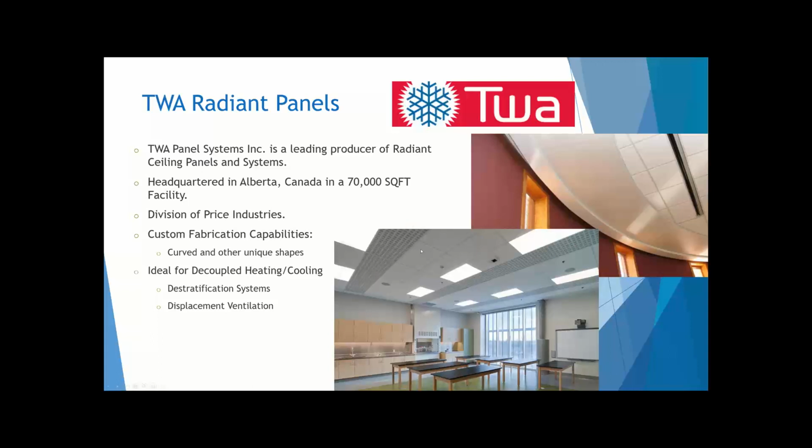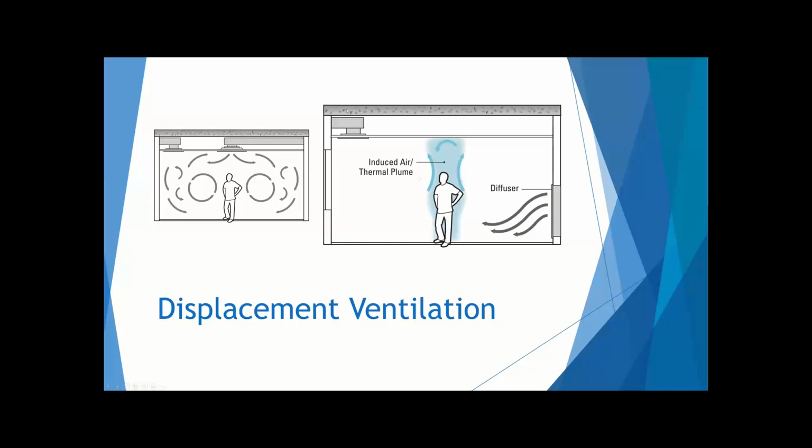So what that does is that heat actually hits the floor, and you're not messing with your system in terms of air movement. You're just simply sending that heat to the floor. It heats the floor, and then that heat comes that way. So pretty cool how it works. Decoupling it keeps that ventilation effectiveness higher in the displacement system. So let's talk about them.